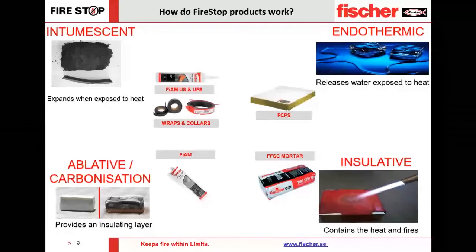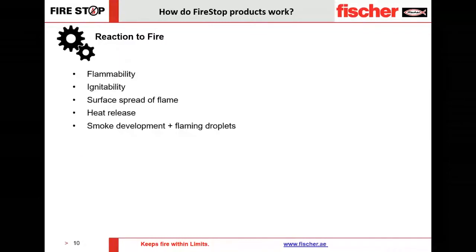There are two aspects that are generally related to fire, which many people get confused with, namely reaction to fire and resistance to fire. When we talk about products or materials, we are talking about reaction to fire. The reaction to fire is the measurement of how a material or a system will contribute to fire development and spread, particularly in the very early stages of fire where evacuation is crucial.